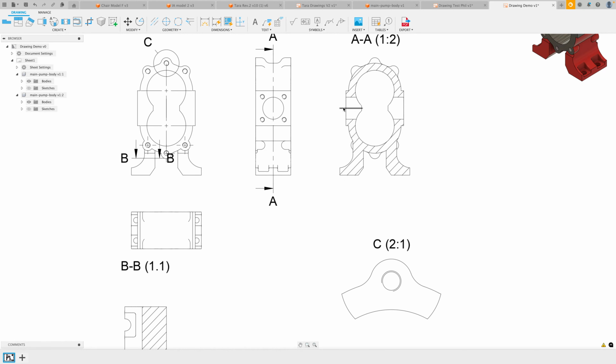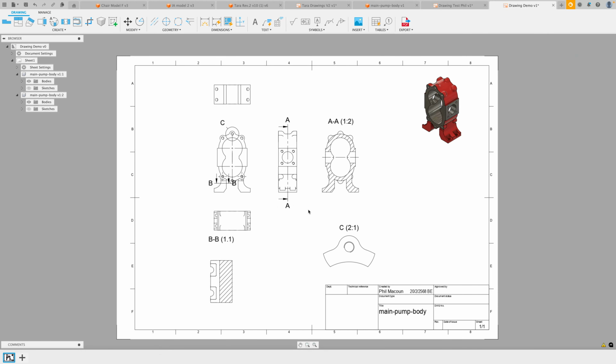Now we're going to re-select that center line without selecting the whole shape, and now I can just drag it through, and I'm just going to eyeball that. And so now I've got a center line that I can use to reference to all the other geometry in this shape. So that is the last step before we add dimensions, making sure that you add center lines and center marks to your circles.